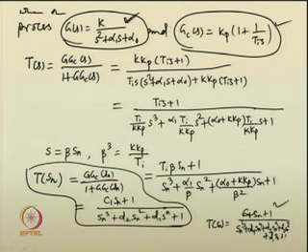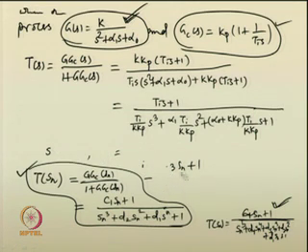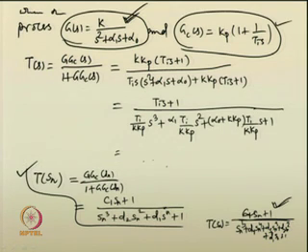So, this is why I am calling it a generalized transfer function: irrespective of the order of the process dynamics, if the process dynamics is available in the all pole form, it is always possible to get the standard closed loop transfer function, having one numerator term and the denominator in this convenient form, sn to the power n plus d(n-1) sn to the power n-1 plus and so on till 1.